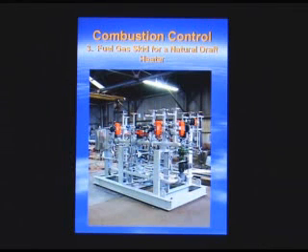There are two separate controls, two separate fuel gas loops. There's a pilot gas loop and a main fuel gas loop. Pilot gas loop is obviously initiated first. You initiate your pilot flame, and then once that's been proven, you're allowed to open your main gas valve to a minimum stop and proceed with lighting the main flame. Once that's proved, then you're able to go through and continue ramping up the burner.